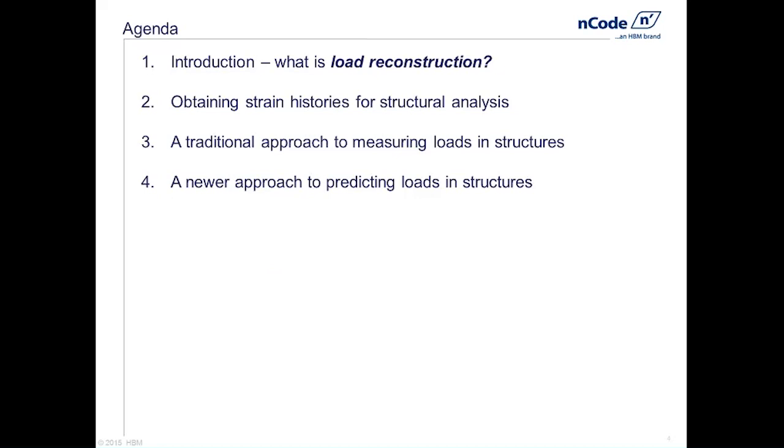How do we come up with an estimate of loads in situ? So from service loading, from flights, from vibration, from usage, whatever it is, proving ground, road loads. What are typical approaches to measuring loads such that we can then analytically look at structural response?